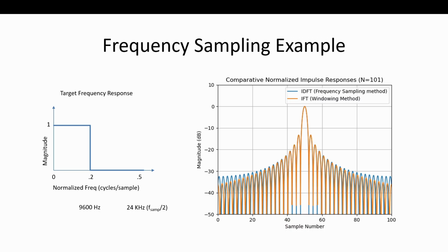Just do anything arbitrary, and it's a matter of having a lot more samples. Whereas this approach, called frequency sampling, says you want an N-tap filter, then you have N samples in frequency. You took the inverse FFT and got your N coefficients. That's frequency sampling. It's not what I just described, where you oversample, and then we can truncate and window just as we do with the windowing method. See the difference?